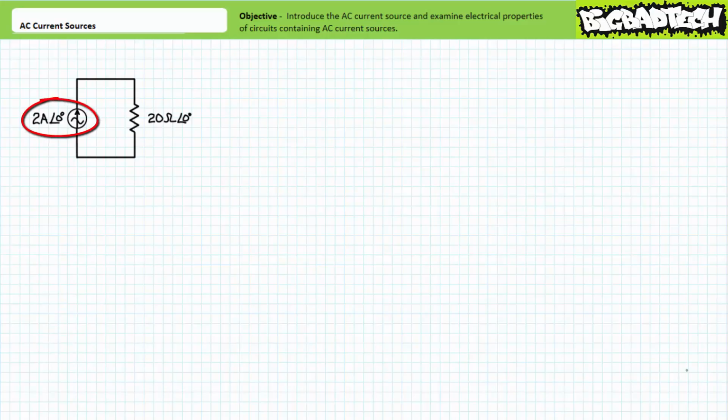An AC current source is a supply element that will push current of a given preset value through a circuit despite changes in impedance. In theory, an AC current source could push 2 amps at an angle of 0 through a 20 ohm impedance as easily as it could a 20 mega ohm impedance, but the real world says differently. We'll discuss limitations of real-world AC current sources in a moment, but for now, we'll just assume AC current sources behave exactly like they're supposed to. Regardless of the applied load impedance, an AC current source pushes the required amount of sinusoidal current through it.